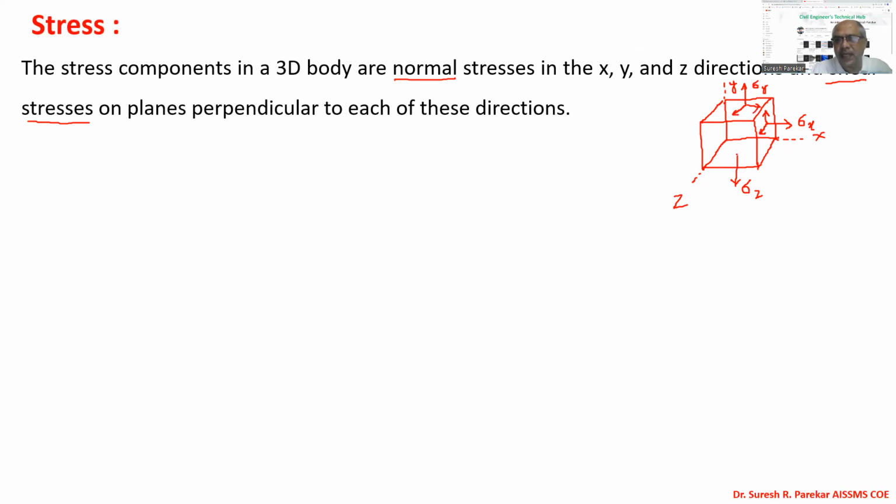And here also you will get 2. So this is sigma Z, actually along this axis. And then 2 we will get: one will be sigma ZX and another will be sigma ZY. So likewise, we have in-plane shear stresses and perpendicular-plane normal stresses.